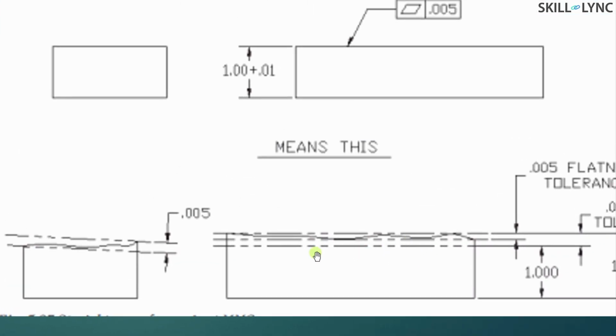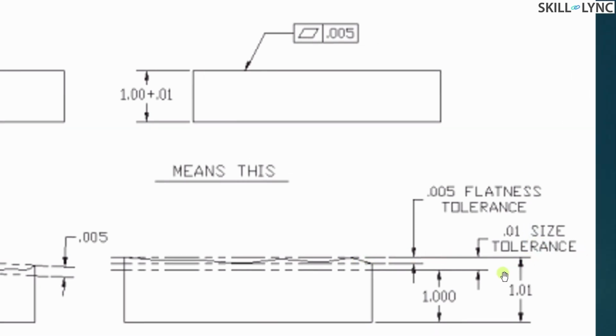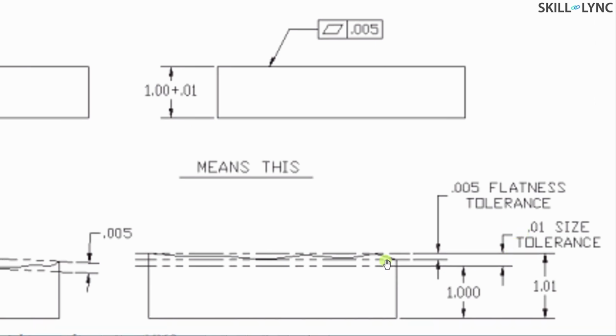In this view you can see this is going to be a base tolerance reference zone, and over and above you have this tolerance zone specification of parallel planes 0.01. So it means with this reference plane, this boundary of 0.05 is the maximum allowed flatness plane within which the object must lie. Likewise, on the lower side we have the other plane that you have drawn here. So this is your allowed flatness zone. Only this is your flatness zone.